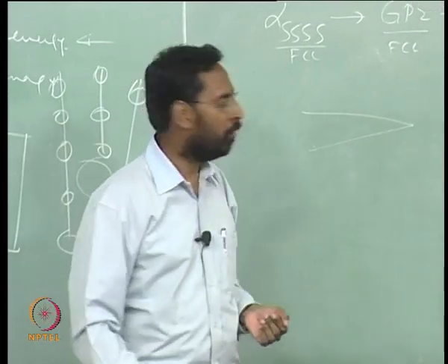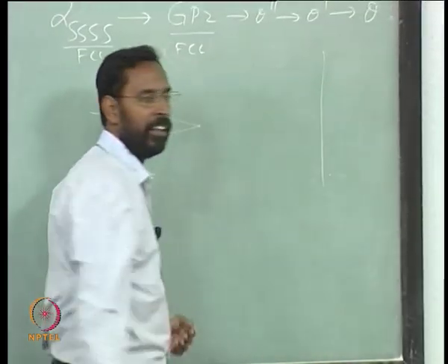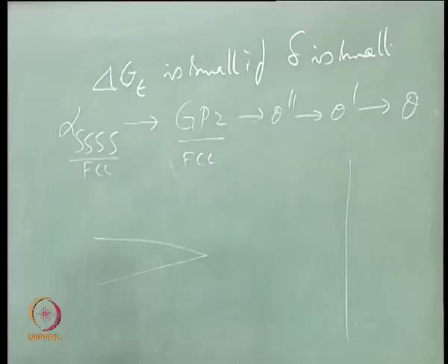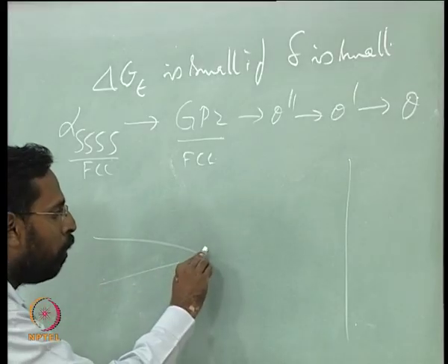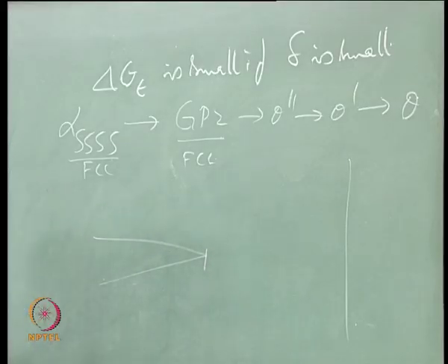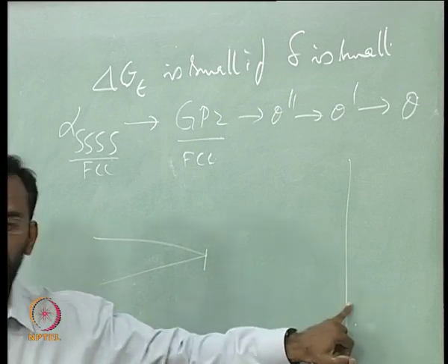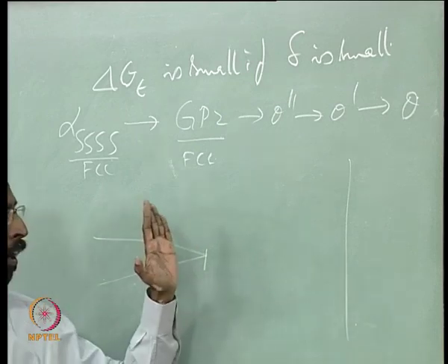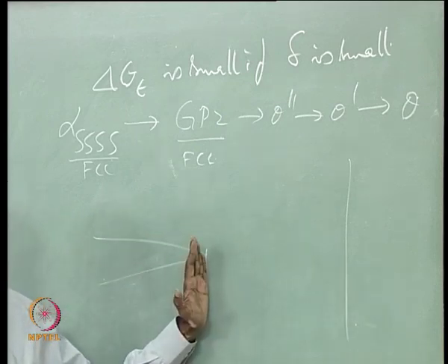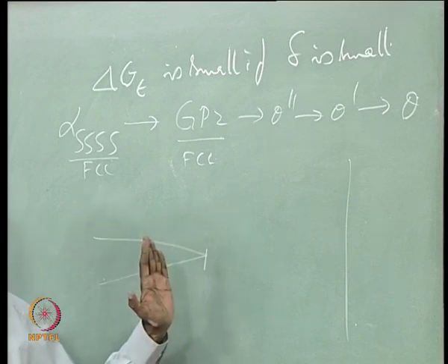So you put a detector at a certain fixed distance and, once you apply a pulsed voltage and you sputter atoms, you try to measure the time that a particular atom has taken to reach here. Once you have done the pulsing, you start your time t equal to 0.